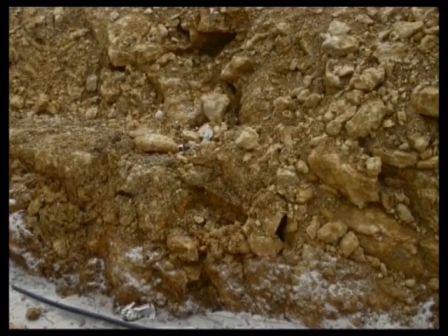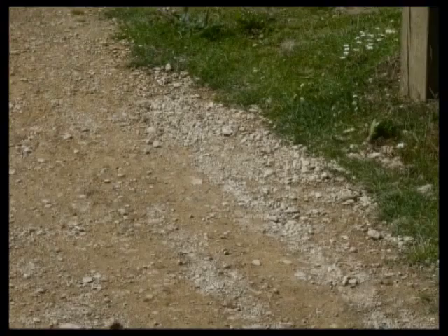Loose rock, providing it's stable and of a consistent nature, can also provide a good foundation and is obviously easier to excavate. Gravels and compact sands mostly have a good bearing capacity, although in ground with a high water table or running water, the finer aggregates may be washed away.